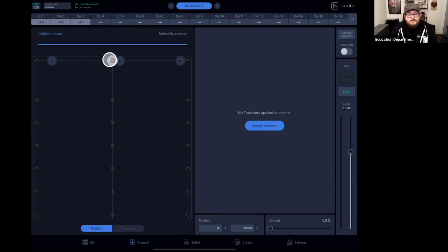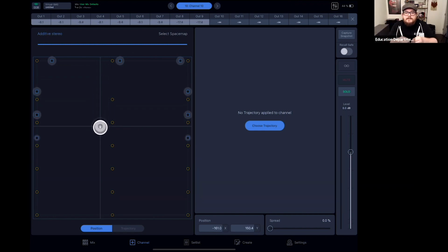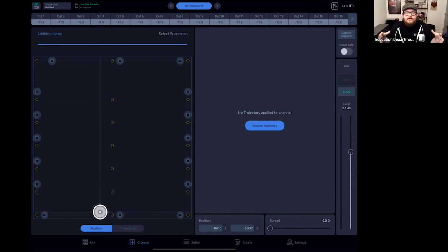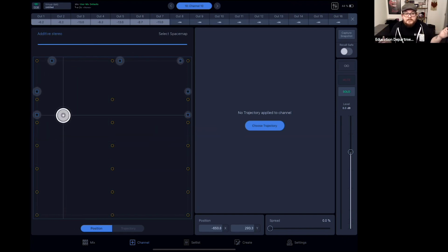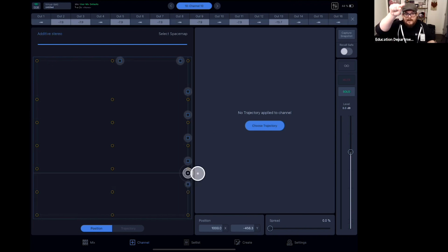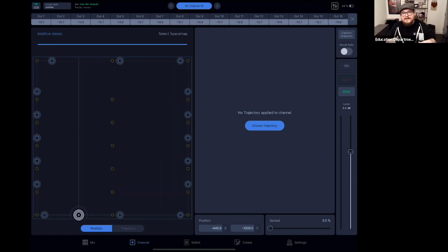The next use of a virtual node, as we said, is that speaker nodes can be connected to multiple virtual nodes. So this is a space map that we like to make called an additive space map. As I move my finger left and right, we have traditional stereo panning, but as I move down, we start adding audio energy to multiple speakers. So very quickly, with the move of a finger, I can now have the audio distributed amongst a large amount of speakers. This map was also used at the stadium and allowed the marching band recordings to move up and down the field quite quickly. And they could also delineate between the home team versus the visiting team side of the field.